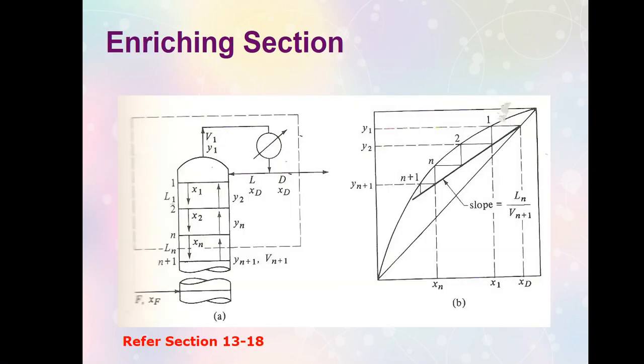Now, there was a mention in the beginning of the topic that your distilling column, or your still, has two sections or zones. The upper section is the enriching section. Of course, the lower section is referred to as the stripping zone. The enriching section, or the rectifying section, when drawn on the 45-degree line and on the equilibrium curve diagram, will be situated here.